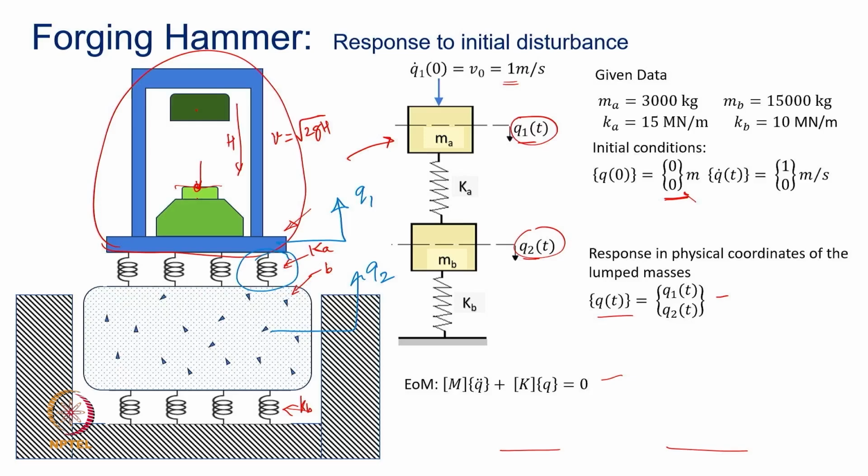right. That also gives you the maximum force that is going to get into the bed, and if you know how much is maximum q2, that also will tell you how much is the force that is going into the ground. Okay. So, all these parameters you can use for ensuring that your mounts selected are going to behave properly, right. If these are helical coil springs, whether they will become solid, given the value of q1 minus q2 at any instant of time, given this kind of an excitation, okay. All of that is basically then your input for iteration in the design process.